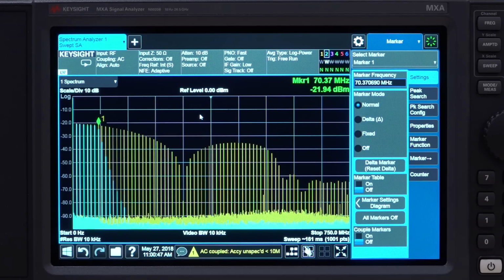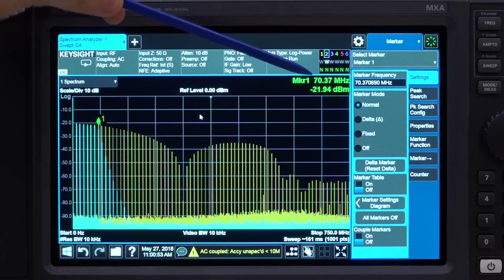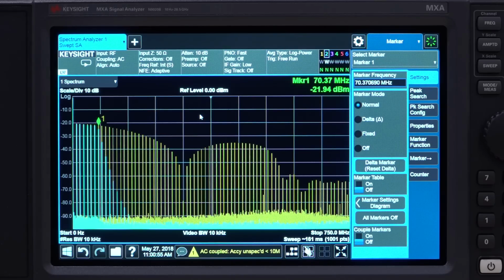time, I'm not going to do that right now, but it gives us a fairly good idea of what the bandwidth of the filter is, and it says that the bandwidth would be around 70 megahertz, and that's exactly correct. This is a 70 megahertz low-pass filter. It has multiple orders. As you can see, the frequency response rapidly drops the amplitude through the filter there, and